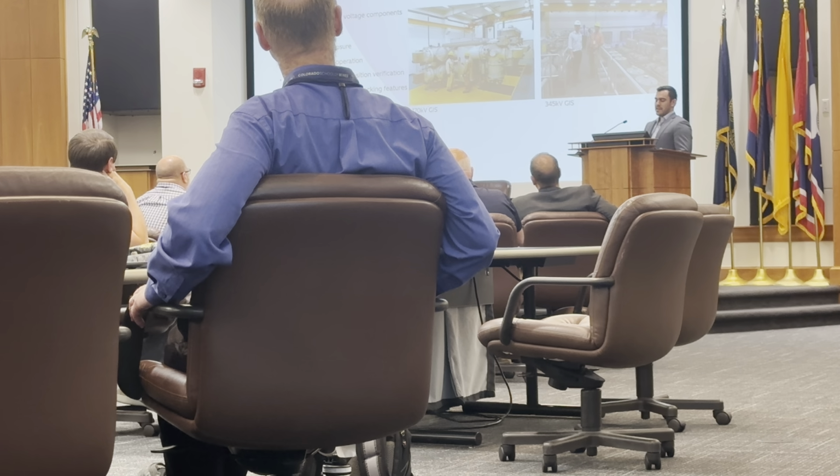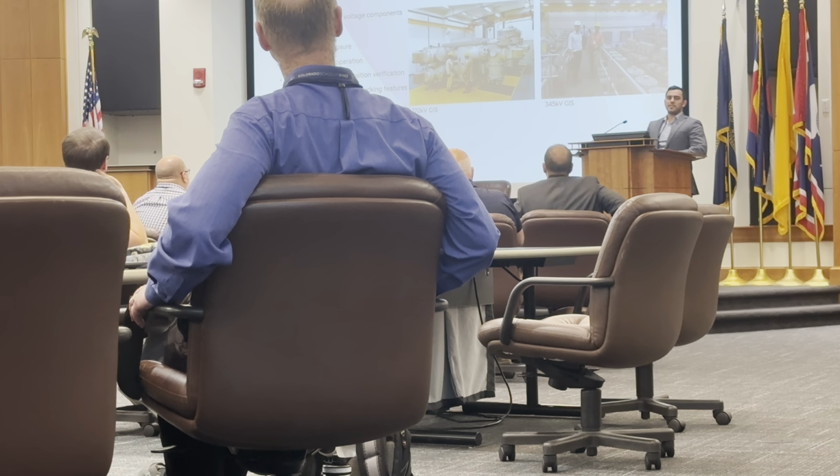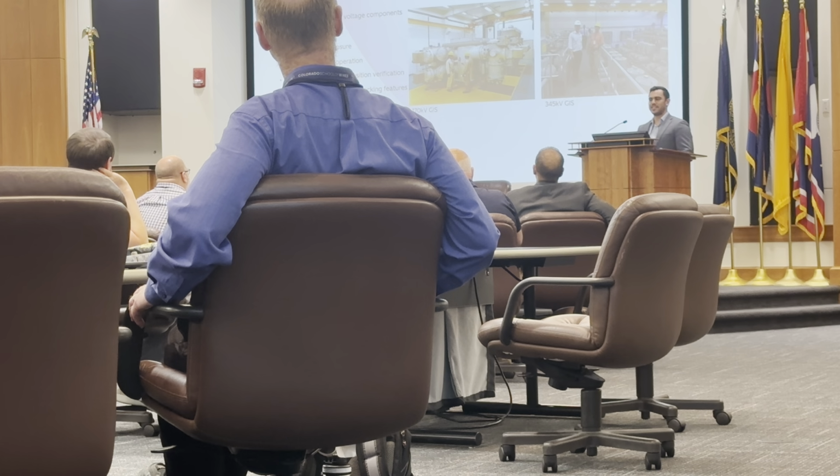And lastly, very important, safety. Safety is our license to operate, so in the long run, we're also thinking about the safety of the people who are going to work at the substation. GIS is safe to touch during operation. Typically, when you're looking at a 230, 345, 550 kV GIS building, the substation has catwalks, stairs, and ladders. And it's safe to walk around.